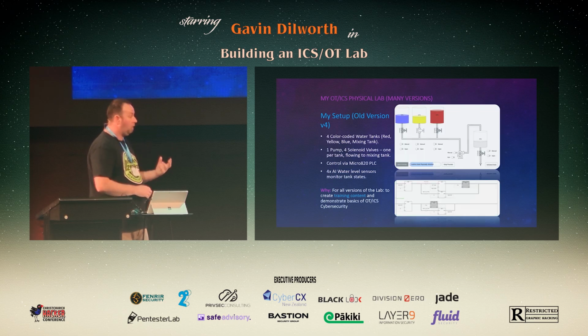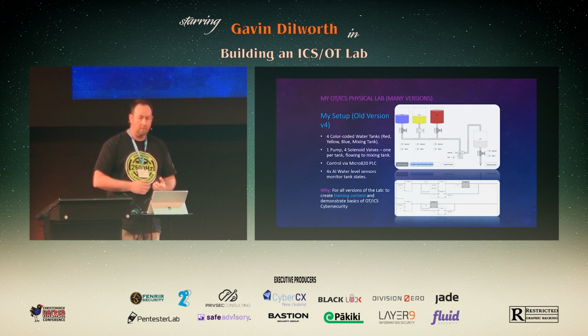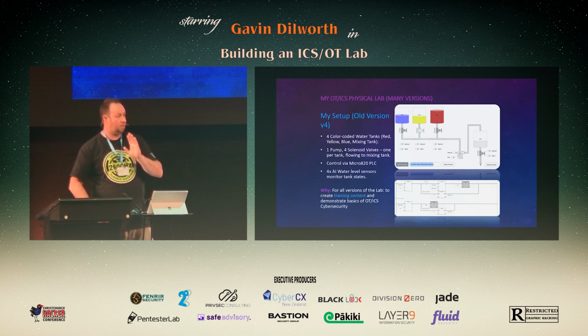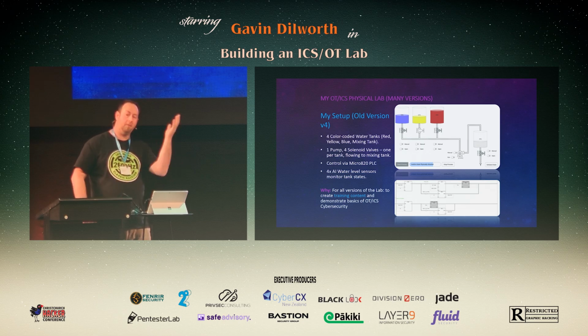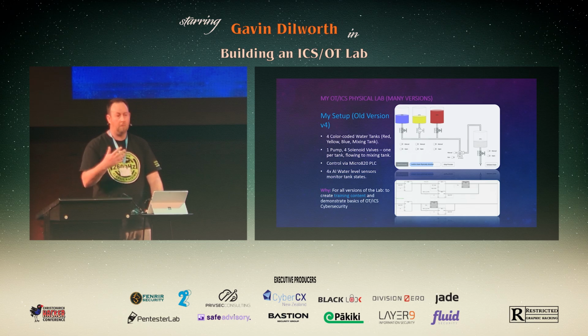I've been doing this a long time. The original concept I had for this sort of lab was back in 2015, where I was going to create something very, very basic with Factory.io and OpenPLC, and connect it through to Kepware, do an OPC UA configuration through a firewall, so I could teach other engineers how to get process data safely through a firewall and explain certificates, because that's what OPC UA uses.